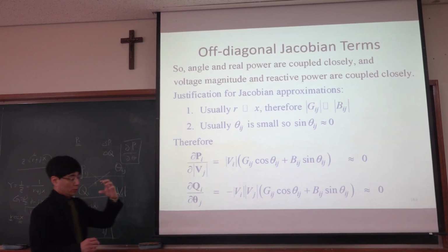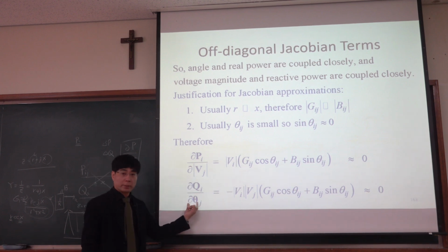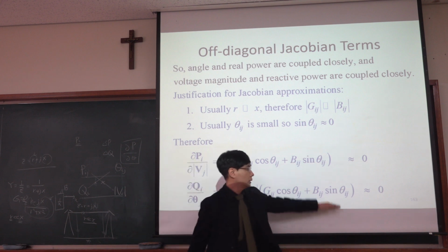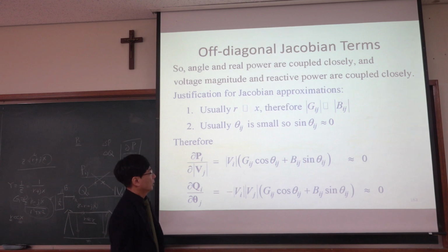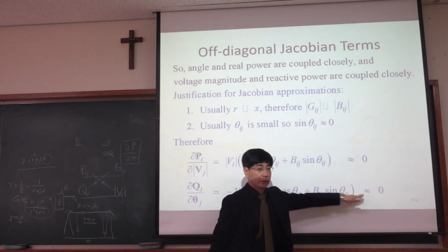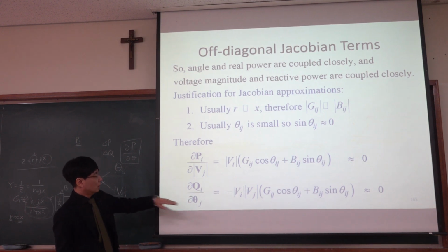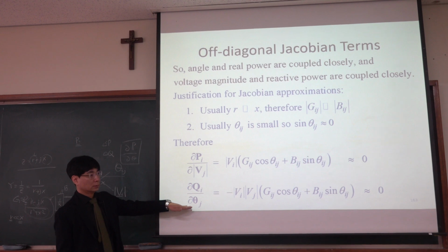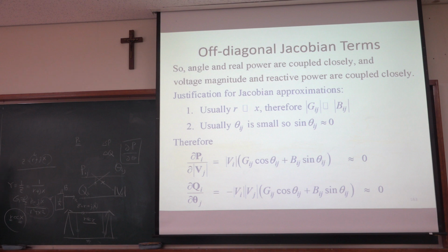Similarly, you have a reactive power equation, and then take the derivative with respect to phase angle, then you have this result. And anyway, this is 0. And yeah, this is also 0, so 0. So reactive power is almost independent of phase angle, mathematically. Assuming this. And in reality, no, this is a reasonable assumption. I saved your homework problem.